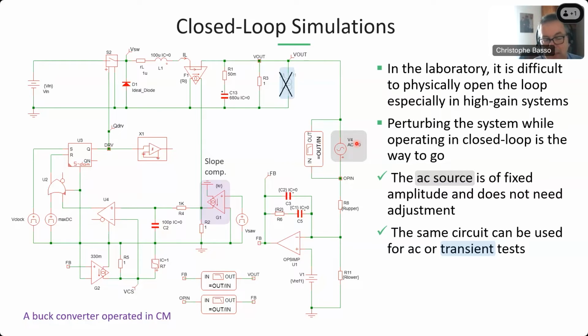And then, as I said, the strength with which the power supply rejects the perturbation depends on the open loop. And we know as a compensation strategy that we're going to have a high gain at low frequency to have a low DC offset on the output. So this high gain is going to absorb the perturbation. So you want to make sure you have sufficient modulation strength at low frequency, but as you approach crossover, we purposely decrease the loop gain.